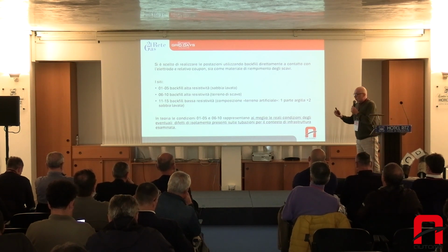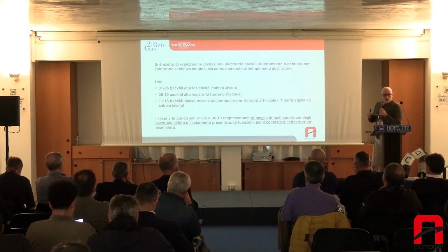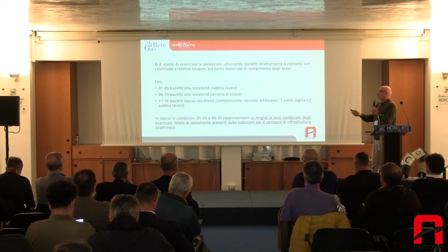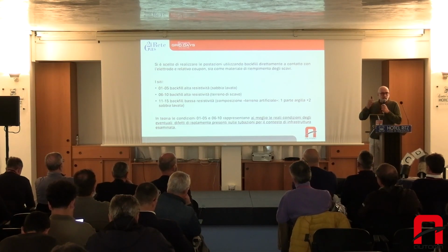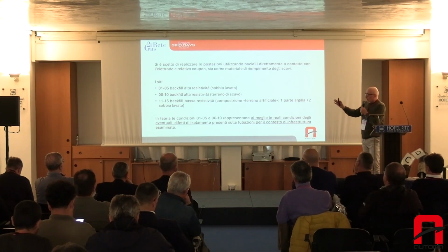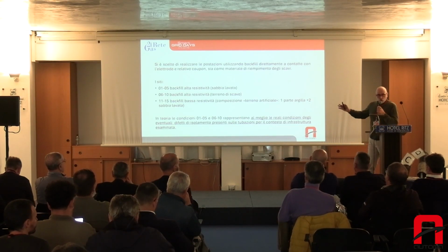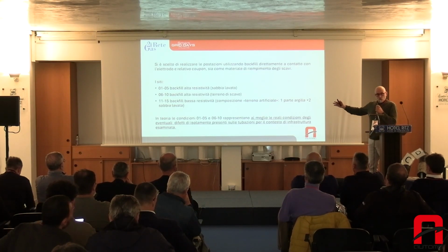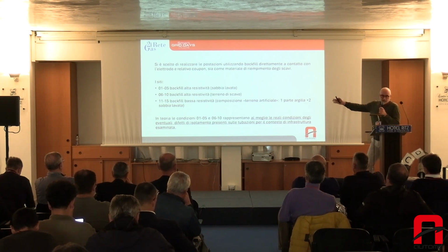And 6 to 10 with high resistivity backfill, and 11 to 15 backfill with low resistivity. 1 to 5 and 6 to 10 are the real conditions of the pipeline. 11 to 15 are a bit forced just to understand what happens when the backfill is different, when the resistivity is different.